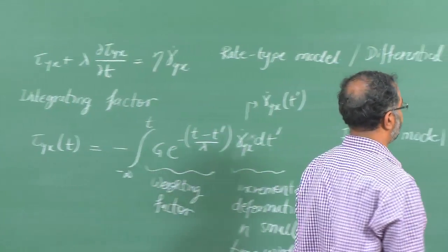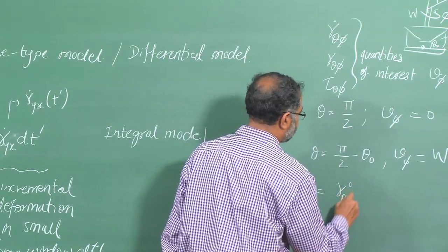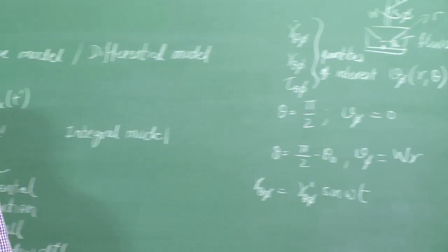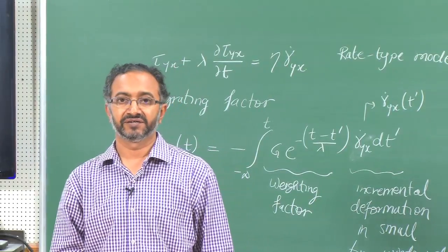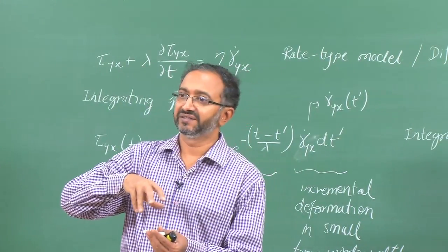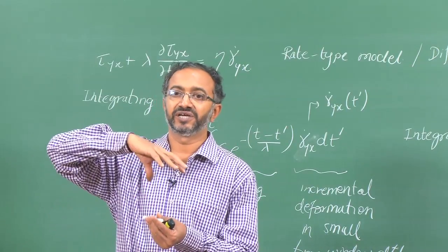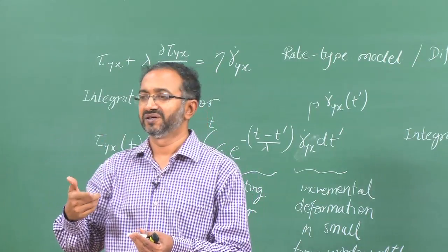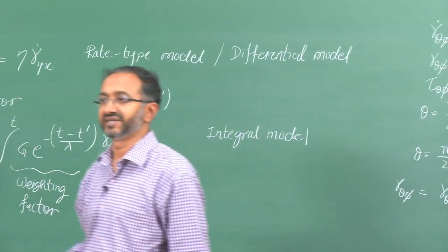And so, what we will look at initially is, let us say, imposing a strain which is an oscillatory strain. So, now the experimental time scale is being manipulated with frequency. If we apply the strain very quickly, then we are giving material very less time to respond to the mechanical stimulus. If we do the experiment extremely slowly, then we are giving the material enough time to respond. So, therefore, frequency which is inverse of time is what is being manipulated in this case.